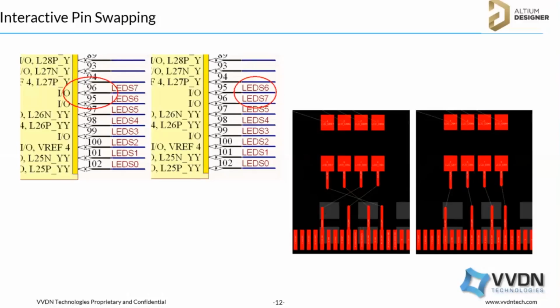So everything I have to take care of. Even the wire annular ring also affects the impedance of the wires and then the signal loss, right? So in that case, if it is acceptable, I think you need to verify with your hardware engineer or software engineer whether we can swap the signals or not.